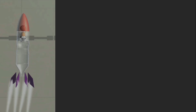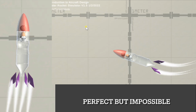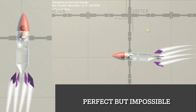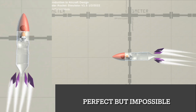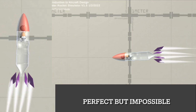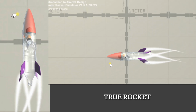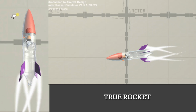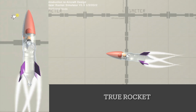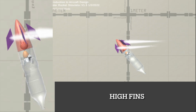The fins on the rocket and the nose cone control directional stability. Directional stability is the ability to return to its initial equilibrium position after a disturbance. Using Unity simulations, we found that the further down the fins are, the more stable the rocket's flight path. This is due to the higher leverage caused by the increase in perpendicular distance, so the rocket returns to equilibrium faster. As you can see on the first video, the optimum fin positions aren't attached to the rocket.